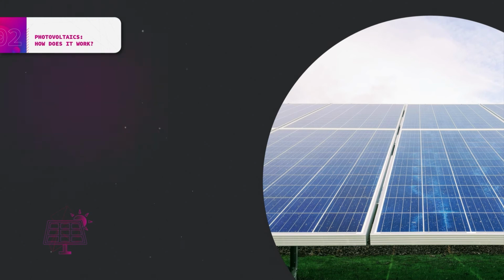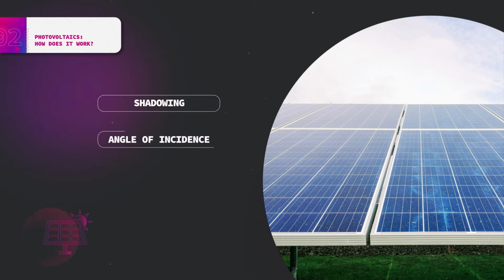Photovoltaic cells and their output power can be influenced by shadowing, the sun's angle of incidence, and their direction. Shadowing reduces the output power, as sunbeams cannot reach the PV cell directly. Despite this missing direct irradiation, the PV cell might still generate a power output, as diffuse irradiation exists. Diffuse irradiation originates from scattering and reflection of sunlight.